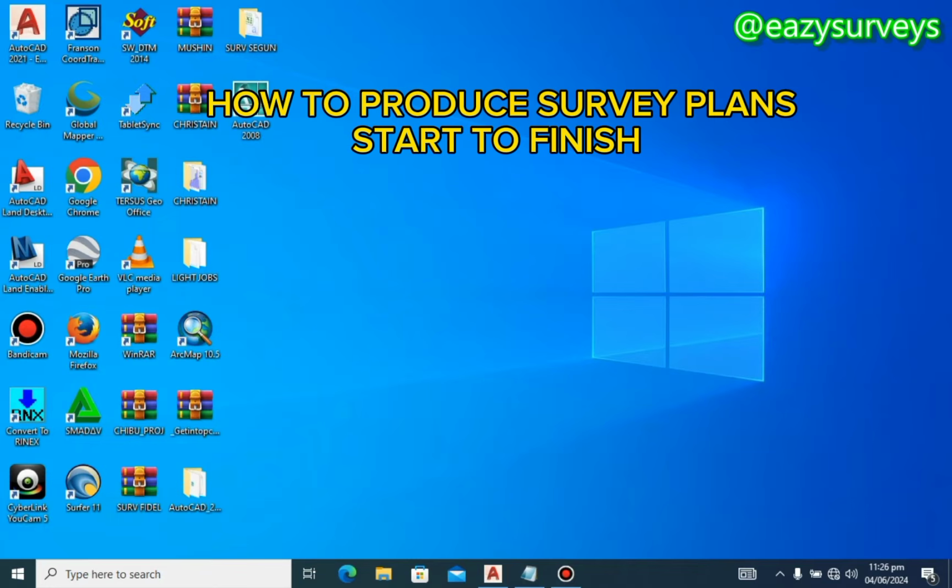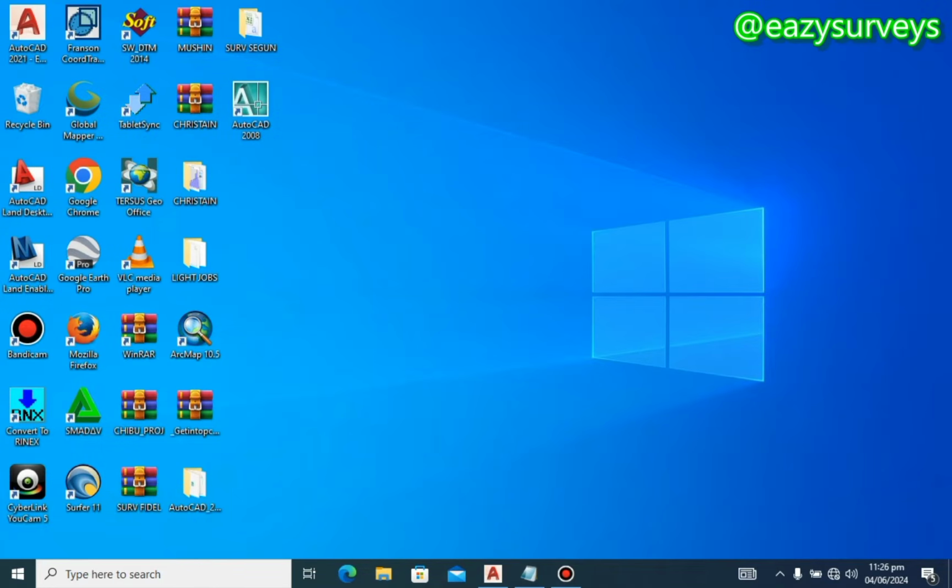All right, so there are different ways to plot survey plans: the running of script method, the coordinate method, and lastly the distance and angles or bearing method. So I'll just quickly show us two of the three methods. The coordinate method and the distance and bearing method is what I'll be adopting.